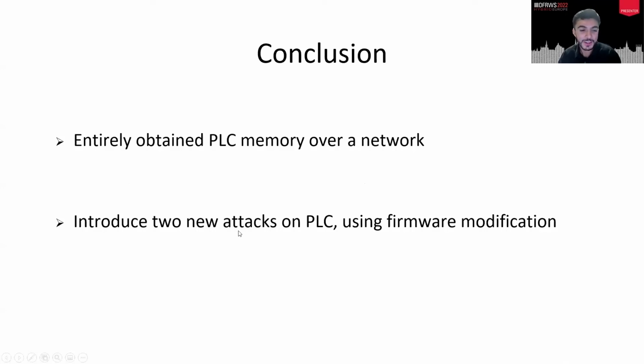And we also introduced 2 new attacks by doing reverse engineering. We were able to do firmware modifications inside the PLC. So even when the control engineer wonders what's wrong with it, he won't be able to tell, because he's writing the right code, but the output of the PLC is always off. It can be confusing.